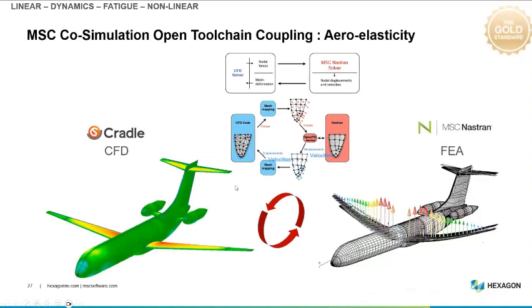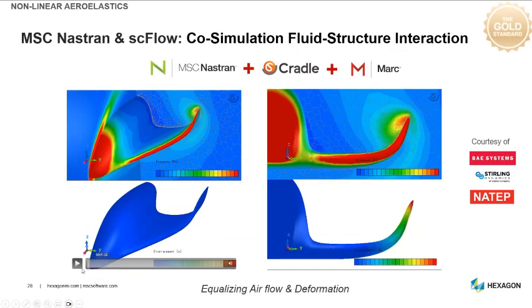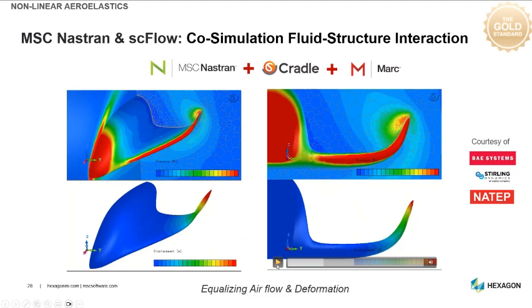So just an example of what's happening in the background. We've got our CFD model, we've got our structural model, and there's some kind of a mapping. The mesh is not the same. Elements, shapes, types, nothing matches. So if this is, for argument's sake, my CFD mesh, just a crude representation, and my finite element mesh, that glue code in between has to take this information and find out what the pressure on every one of these elements is. The FEM software, on the other hand, calculates displacement, which is then passed back to get the deformed shape for the structure.